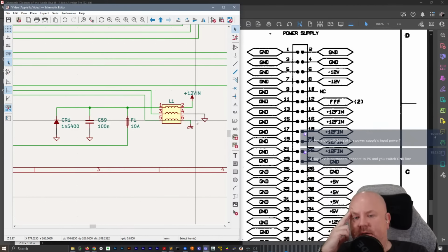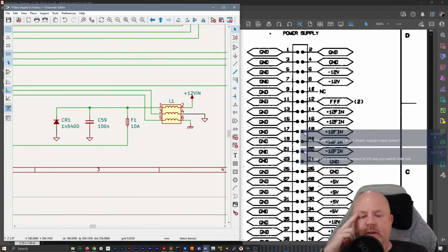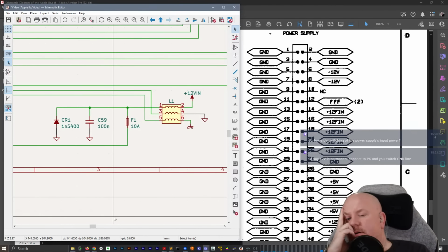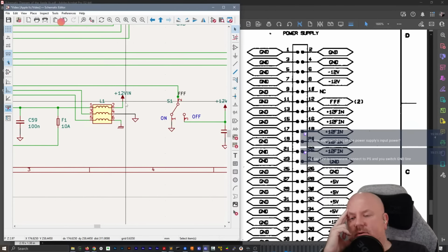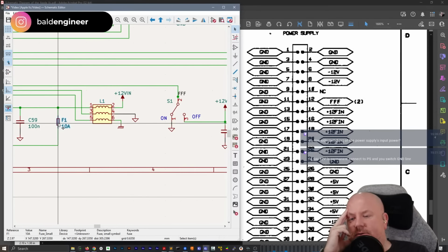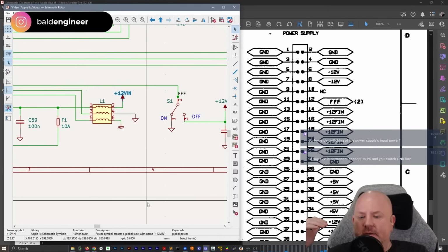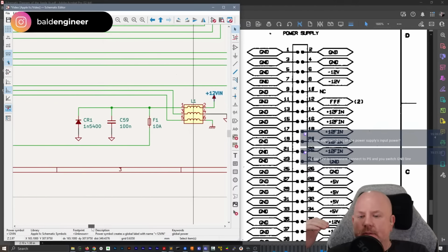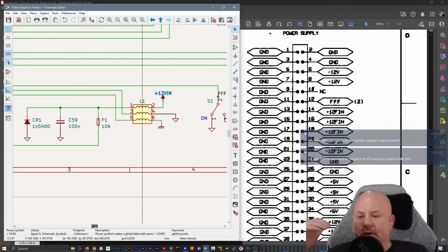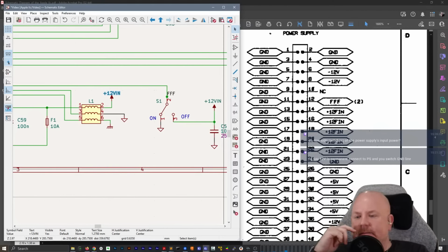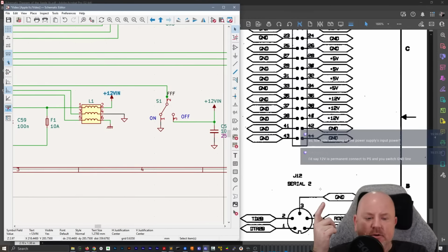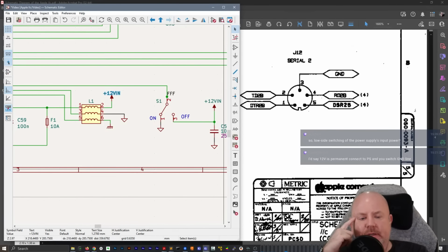And there's no regulator, as far as I'm aware of. There's no, wait, there is a 12 volt regulator on this board. I mean, the fact that this 12 volts comes in through this filter and this fuse really makes me think that EEE is the only way we get from the barrel jack into the 12 volt line. And this doesn't show the power. Well, this wouldn't show power though, would it?